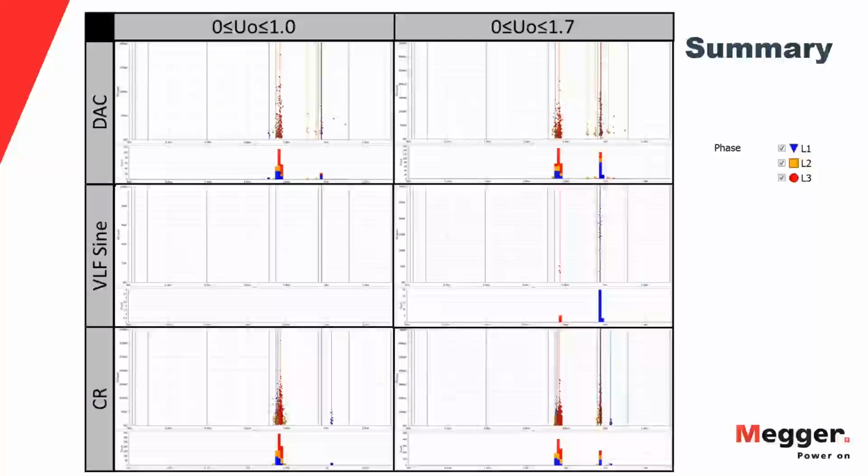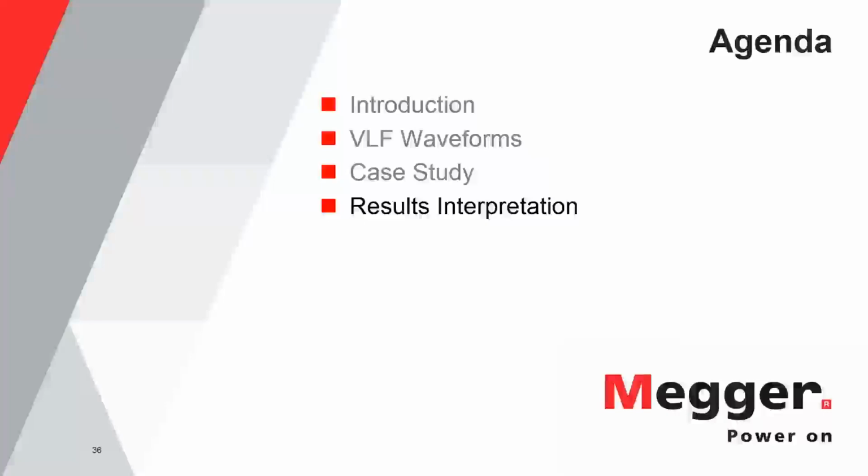However, what you do is you try to gain scientific data for the risk assessment, and what these people were doing after fixing those splices, or at least improving the quality, is monitoring those cables now a little bit more often than before to see if that spot develops into a more severe spot. So there was action taken after that, because it was unclear if the PD activity was on the oil side, on the wet side of the transitional splice, or on the dry side.